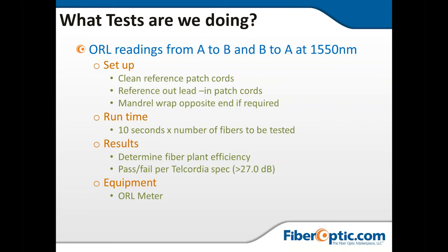We're going to reference out our patch cords, and we're going to mandrel wrap the opposite end if it's required in the reference process. The run time is about 10 seconds per fiber. Doing this, we will be able to look at the amount of reflection and which side the reflection's on, which is going to tell me which side's the connector dirty.